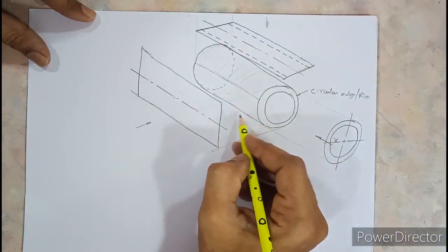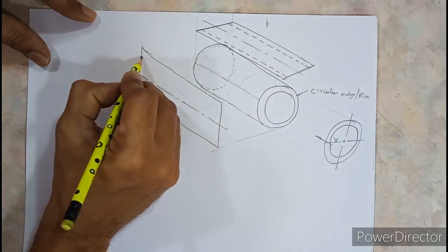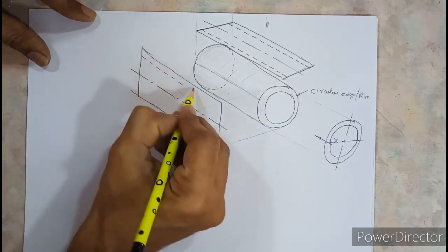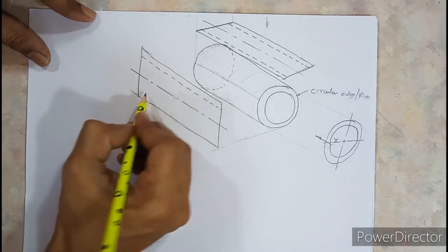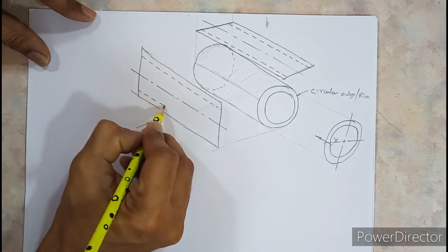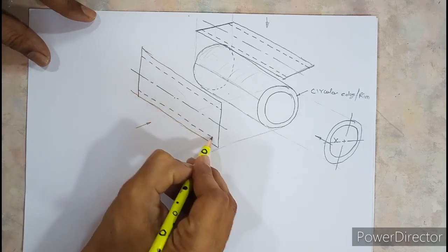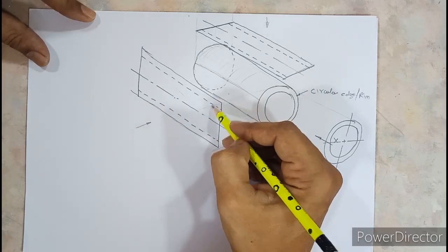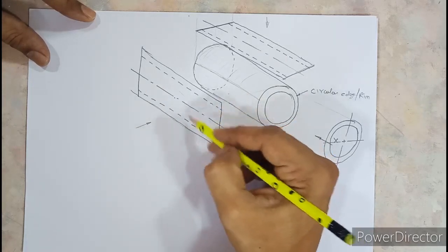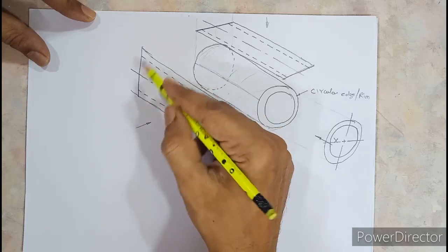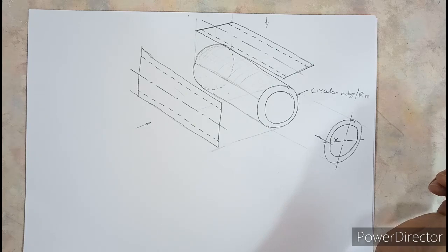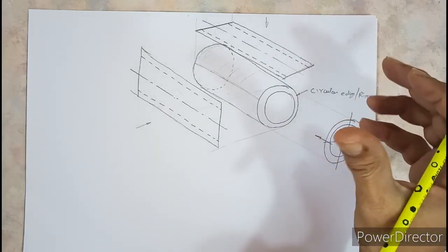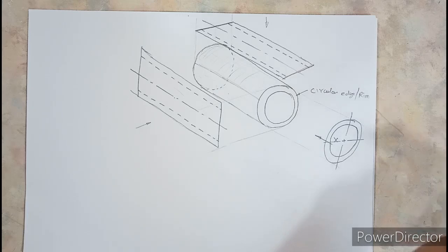Similarly, if you look in the side view from here, you will find a broken line here, that is a hidden line here, and another hidden line will be over here on this side. So both the hidden lines represent that there is a circular cavity which is going in throughout. So that is how a cylinder is represented. I hope the views are clear, and as we proceed, you'll understand circular surfaces much better.